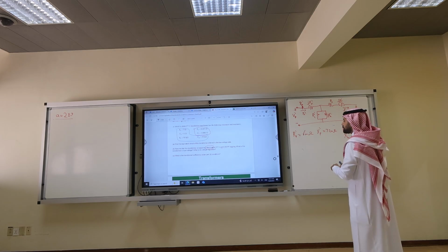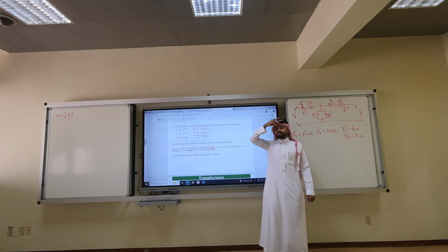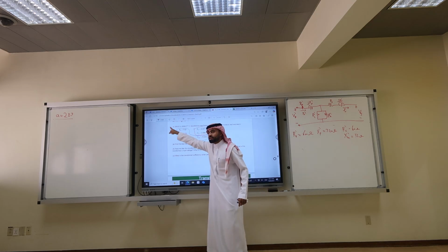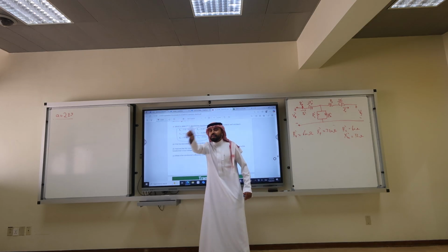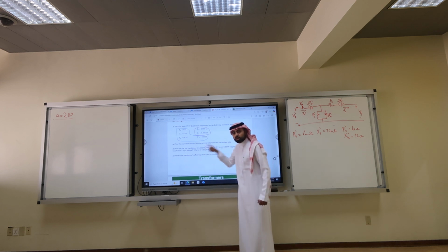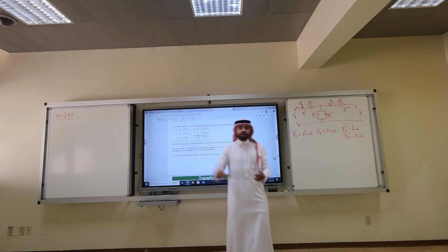Now, what will happen is, in the previous problem, what did we use for the load? What power did we use? He already told you the power was consuming 20 kilowatts. Now he didn't tell me. So what is the power that the load consumes? The rated apparent power of the transformer. Get it? That is why I need to panic whenever I read the word rated, because it has lots of information inside it. It means the load that is connected is by design whatever the transformer is providing.